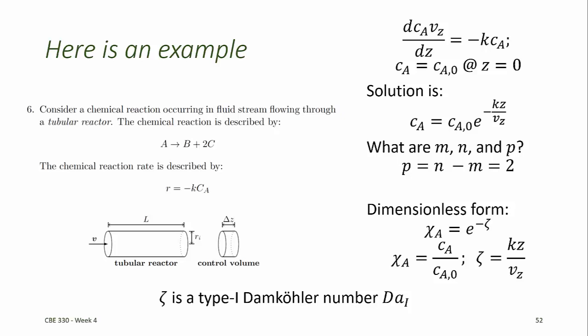In this example, we derived the dimensionless quantities from the model equation itself. The Buckingham Pi theorem can also be used to derive dimensionless quantities when we don't even have a model equation. This is very useful for developing empirical models because it can reduce the number of variables required in the model and therefore simplify the model.